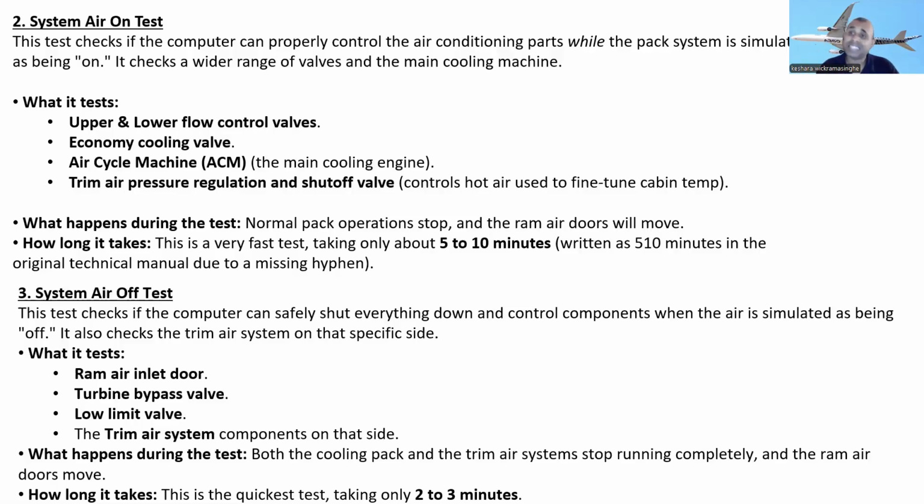All right, so what is tested? They test the ram air inlet door, turbine bypass valve, low limit valve, and the trim air system components on that side. All right, so what happens during the test? Both the cooling pack and the trim air system stop running completely and the ram air doors move. How long does it take? This is the quickest test, taking only 2 to 3 minutes.